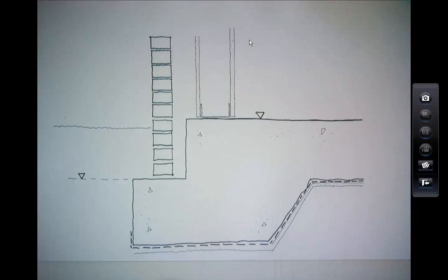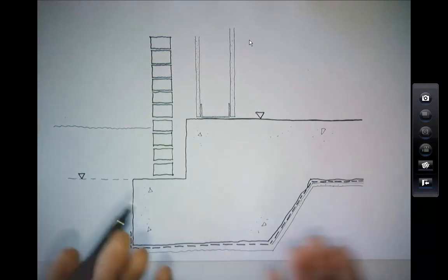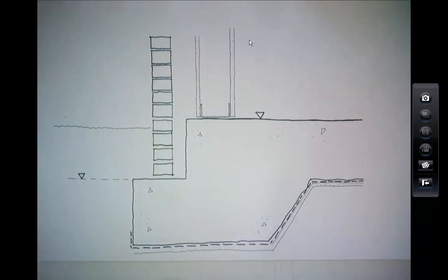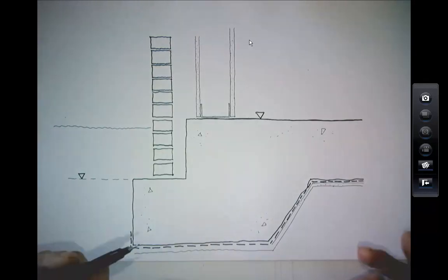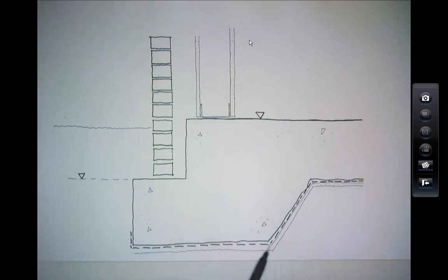from being punctured, because then below that you'll have some rubble, some hardcore. Or if you're insulating below the slab, this would be insulation. Okay, you often end up not insulating below the slab because you don't need it, because you've got the effect of the thermal mass of the soil. Often it's actually not that important. Sometimes you do, but not always. Okay, so that's just our sand.